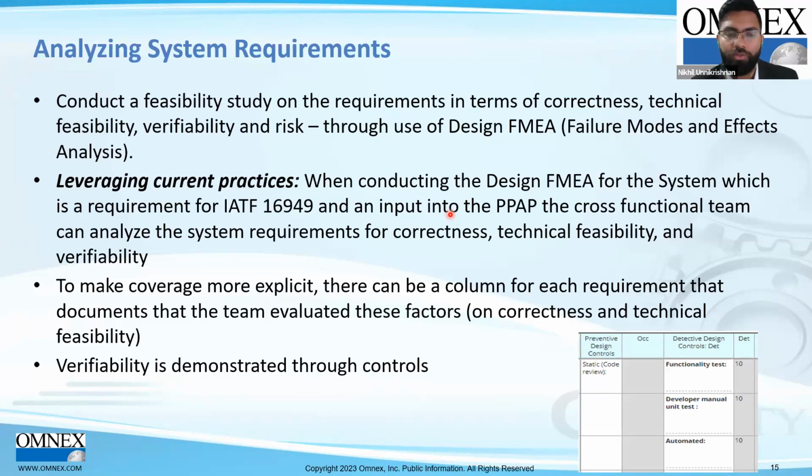They have talked about how earlier, if you look at the 4th edition, you're typically looking mainly at that particular focus level. But for example, with the newer FMEA approaches like the AIAG VDA, you're looking at the information you have at the higher level and also the information at the lower level. So both are being considered. So that is how DFMEAs have also evolved to support the V model as time has gone by.